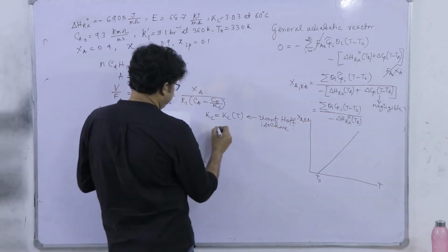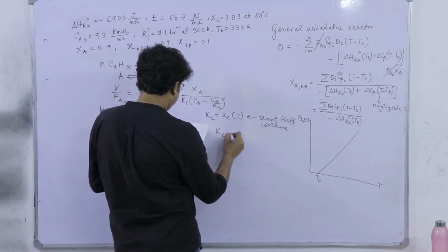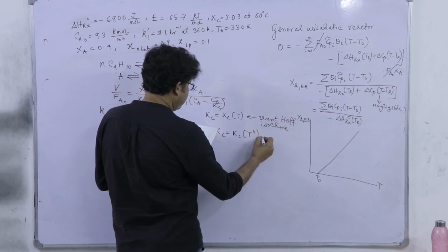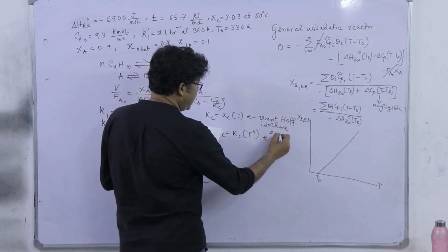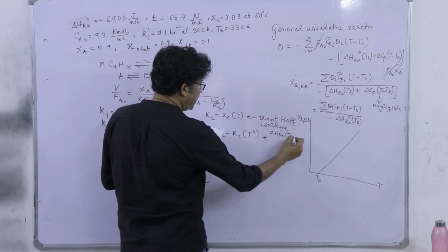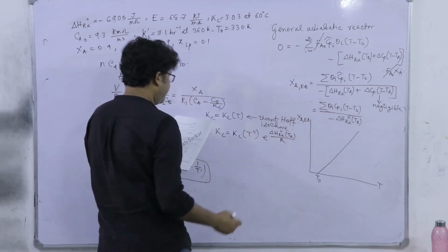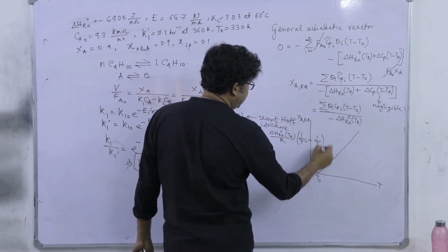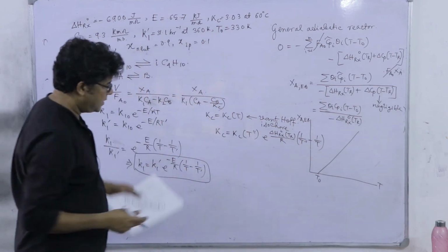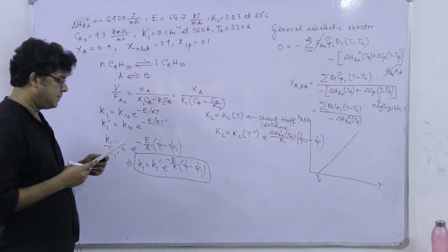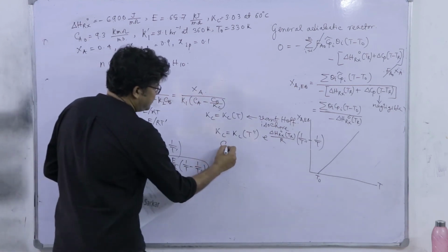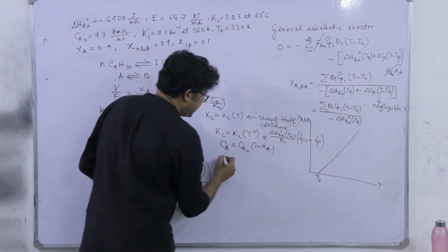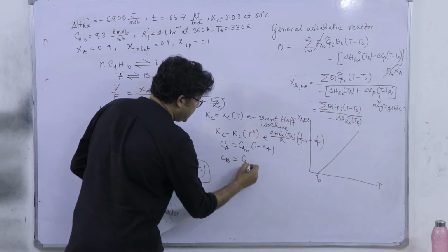And that relation we can simplify as Kc at T double prime into exponential of delta H Rx naught at Tr divided by R into 1 by T double prime minus 1 by T. So, that is the equilibrium constant thermal model. And stoichiometry gives you Ca equal to Ca naught into 1 minus Xa and Cb is equal to Ca naught into Xa.